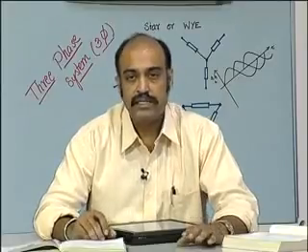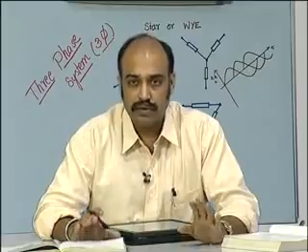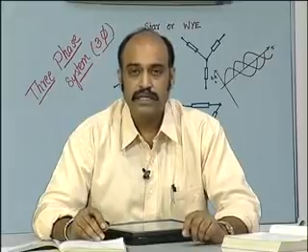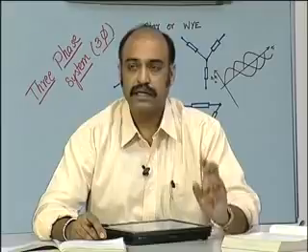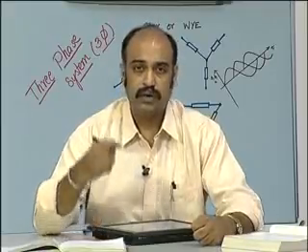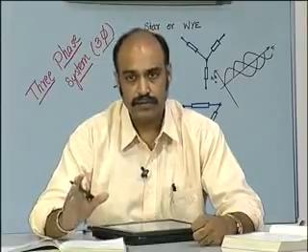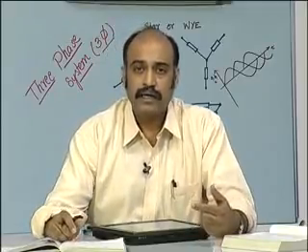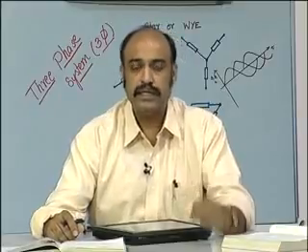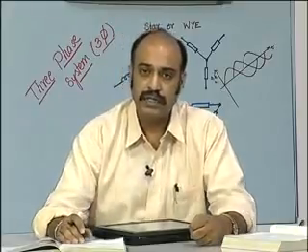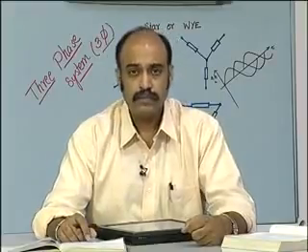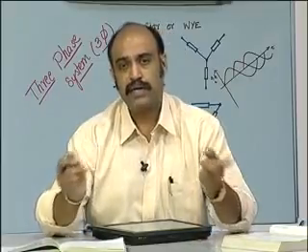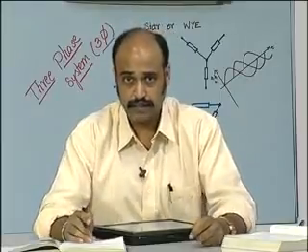The DC generators and DC motors are a class by themselves. They both are similar machines, similar in structure, but the only difference being that in the case of the DC generator, the energy is input in the mechanical domain, you are taking out the energy in the electrical domain, and therefore, from the electrical domain point of view, it is a generator. And in the case of the DC motor, you are applying the energy input in the electrical domain and taking out the energy in the mechanical domain. But constructionally, both the machines are very similar, and a DC generator can be operated as a DC motor and a DC motor as a DC generator, vice versa.